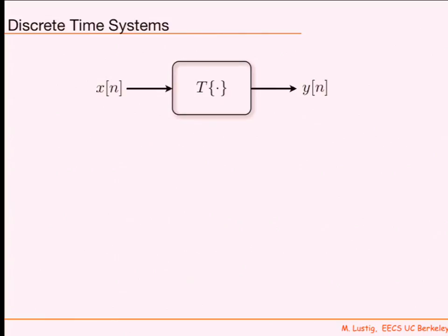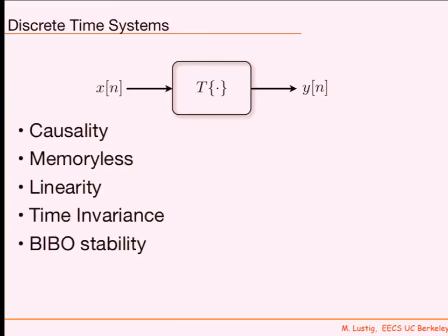We talk about properties. Remember properties of these systems? Causality, memoryless, superposition, linearity, time invariance. What kind of stability? BIBO stability. And what is BIBO stability? Bounded. That's great. You see, I don't even need to teach this class today. BIBO stability is bounded input, bounded output.